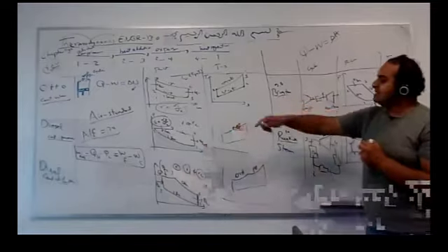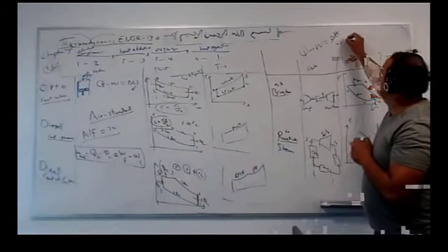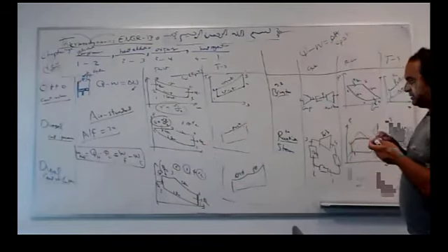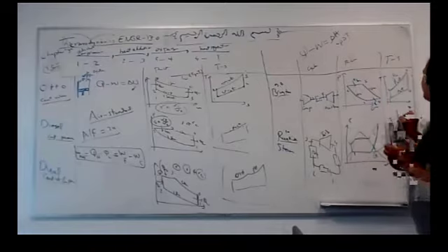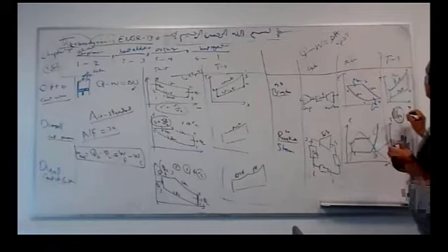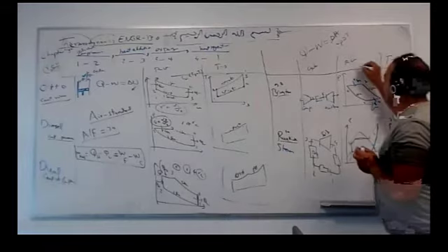For Brayton, which is gas, the same as the others, this is Cp delta T. If you have mass, both mass, I mean in extensive property, not intensive. But for Rankine, no, we care about enthalpy H. We care about temperature. Whenever you have a cycle, make sure at every state you have temperature.